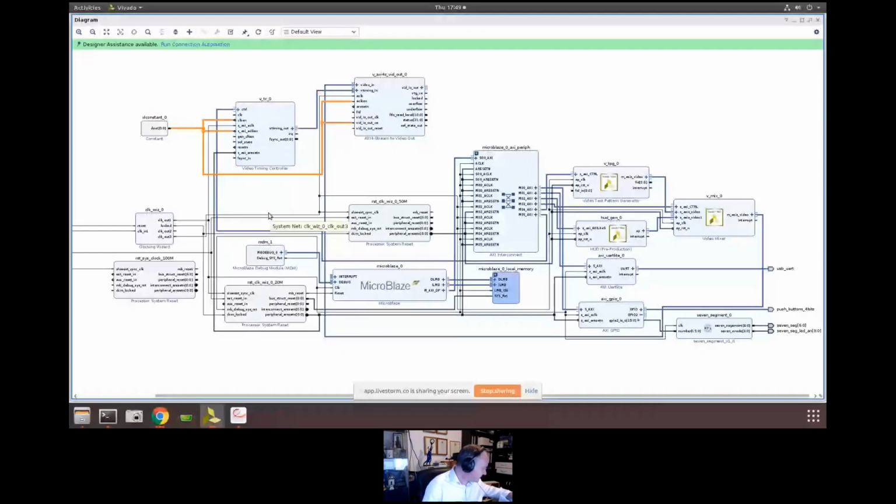Okay, VTC's clocks, that's all done. We're going to connect the VTG CE pin here back to the gen clock enable here. This allows the video stream to output to be able to put back pressure on the timing controller and adjust it slightly. And we're going to connect the SOF start of frame output to the SOF state there as well.